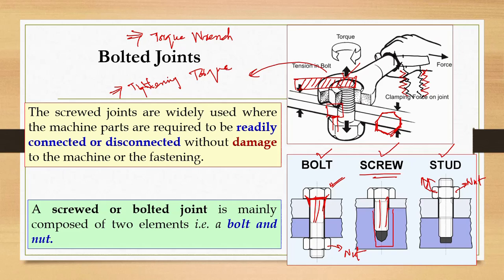They're expensive, but torque wrenches are used in most sophisticated environments, like car assembly plants, or where a large machine is being manufactured. With a torque wrench, you can set a torque as much as you want, and when this torque is achieved, the wrench indicates it with a clicking sound, like tick tick tick. It does not make a sound if the torque is not achieved.